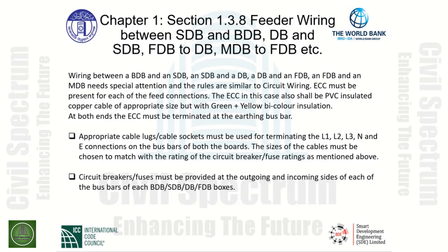Section 1.3.8, titled Feeder Wiring between a Sub-Distribution Board and a Branch Distribution Board, a Distribution Board and a Sub-Distribution Board, a Floor Distribution Board to a Distribution Board, a Main Distribution Board to a Floor Distribution Board, etc. Wiring between these distribution boards and a main distribution board needs special attention, and the rules are similar to circuit wiring.